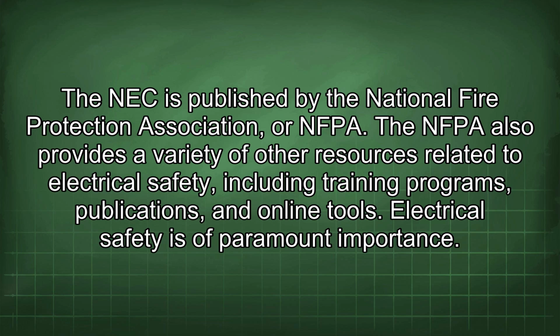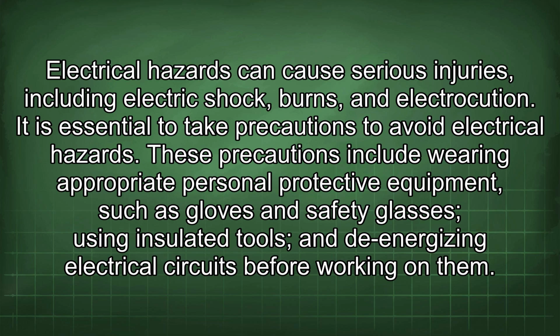Electrical safety is of paramount importance. Electrical hazards can cause serious injuries, including electric shock, burns, and electrocution. It is essential to take precautions to avoid electrical hazards. These precautions include wearing appropriate personal protective equipment, such as gloves and safety glasses, using insulated tools, and de-energizing electrical circuits before working on them.